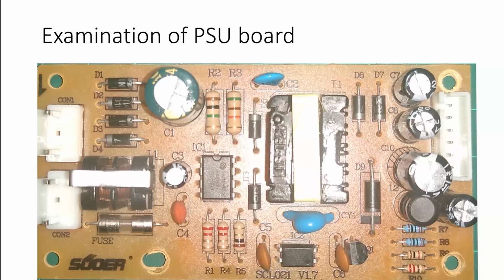Right down the center of the board there, underneath that transformer, I anticipate seeing a gap where all the high voltage stuff is to the left of the board as we're looking at it now, and all the low voltage stuff is to the right. And there should be an isolation gap to keep the high voltage stuff and the low voltage stuff separate, to stop the high voltage stuff from destroying the low voltage side.